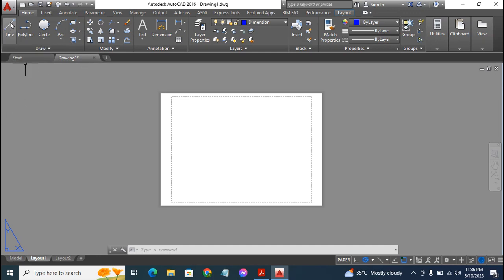All right, click line on the draw toolbar. Click line starting off from this edge. Ensure the cursor locks to the edge of the paper. Then click on it. Enter a distance of 10 millimeters. Type in 10, press enter on the keyboard. All right, then go to the horizontal 10 millimeters upwards, ensure it locks at 90 degrees and 10 millimeters, then join this point of intersection 10 millimeters.